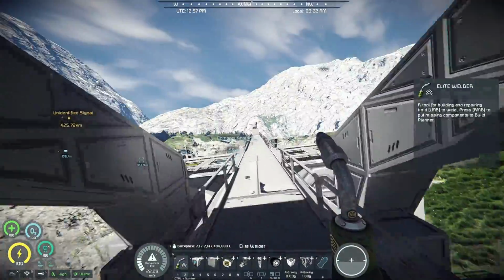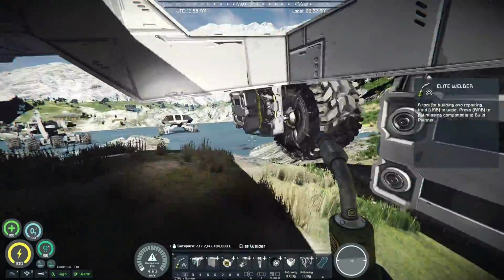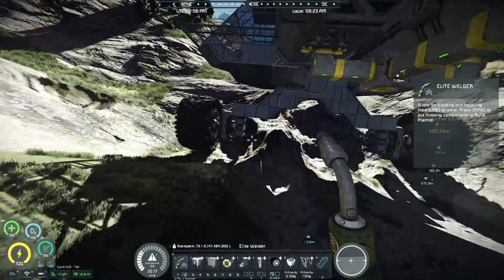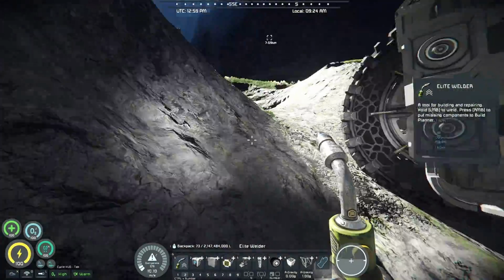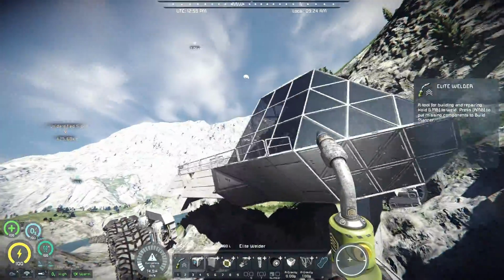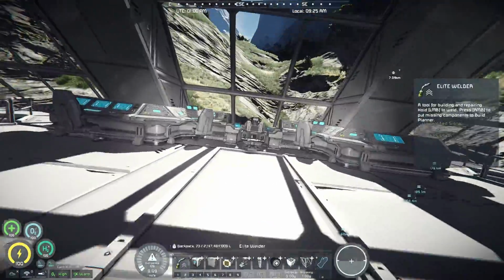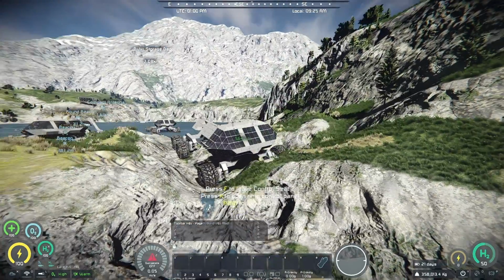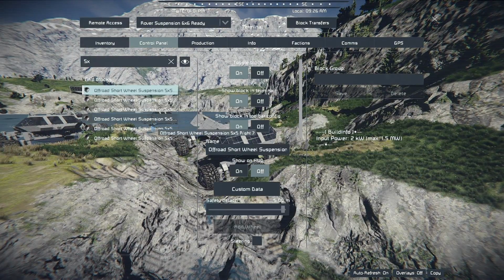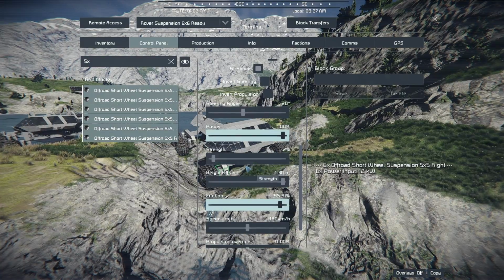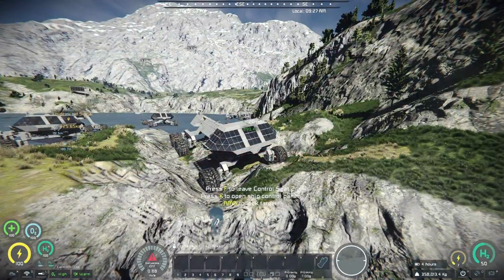Actually, let me demonstrate what I mean. This block is in contact. This block's in contact also when we're trying to move further. Alright, you're probably saying that we need to increase the strength of our springs a little bit. Let's do that, and increase it, for example, to standard 6, yeah?